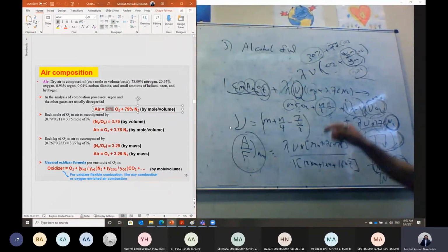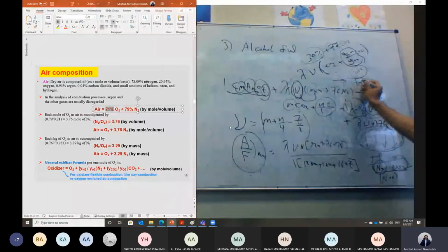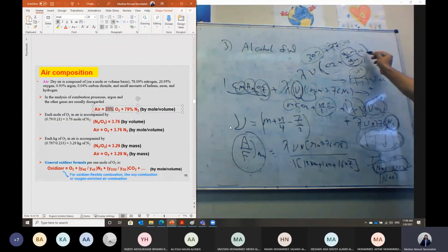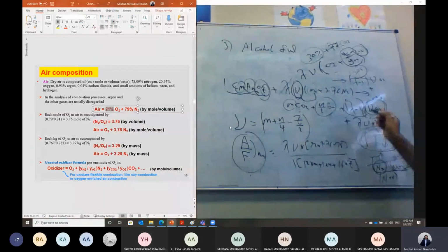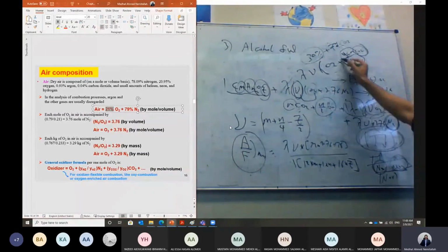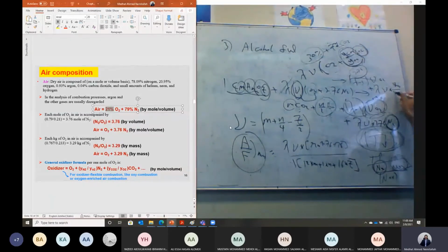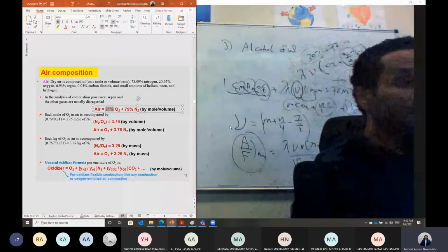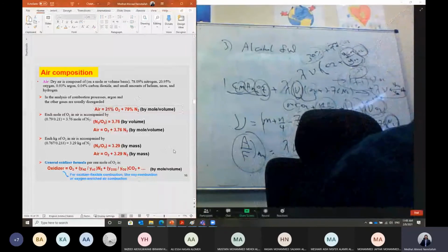And in this case, the combustion product will be lambda minus 1, the same by gamma O2, plus, instead of nitrogen, CO2, which is considered an inert gas as well. So in the product it will be lambda by gamma multiplied by this ratio, which is YCO2 divided by YO2, from the carbon dioxide, which is CO2. Okay, is that clear, guys? So this is the generalized equation for the oxidizer, and it may come to your exam.